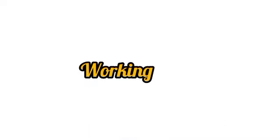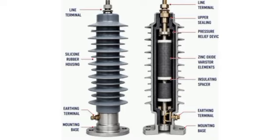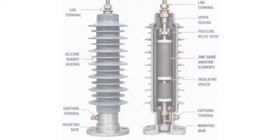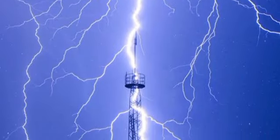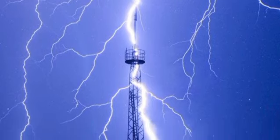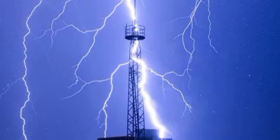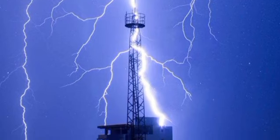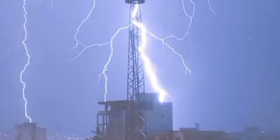gaps. Working steps. Under normal voltage, the lightning arrestor acts as an insulator. A lightning strike creates a high voltage surge on the power line. The arrestor senses the excessive voltage and becomes conductive. The surge current flows safely through the arrestor to the earth. After the surge disappears, the arrestor returns to its insulating state. The power system continues operating normally without interrupting the supply.